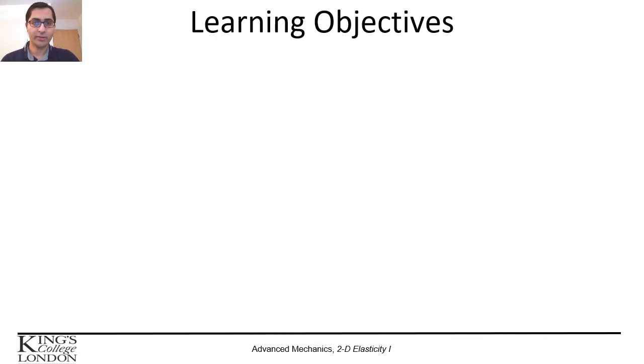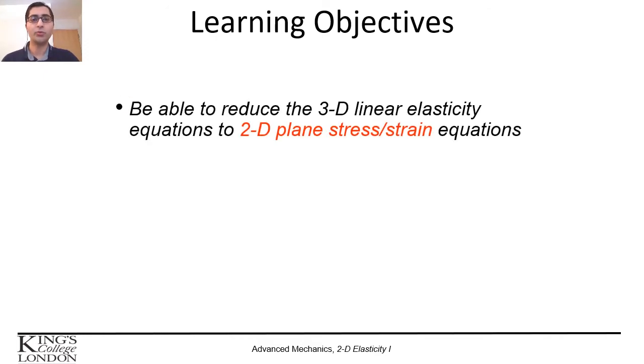Learning objectives are be able to reduce the 3D linear elasticity equations to 2D plane stress-strain equations. Last session, we solved the 3D linear elasticity equations for some simple cases, but today we're going to learn how to even more reduce the complexity of some problems by reducing the 3D geometry to 2D geometry.